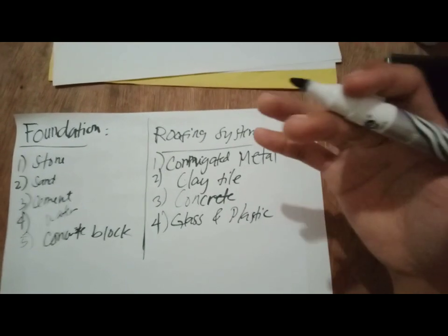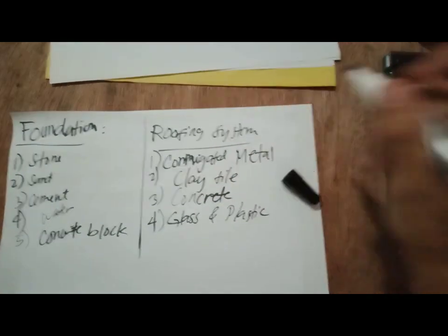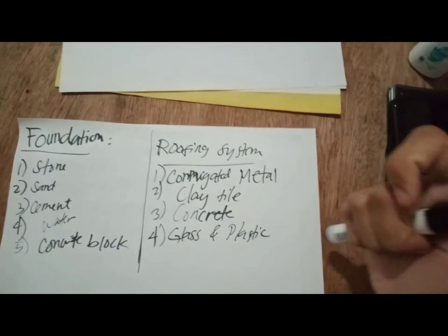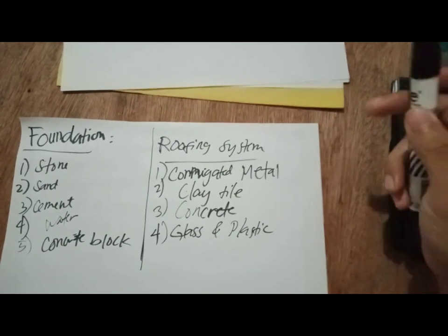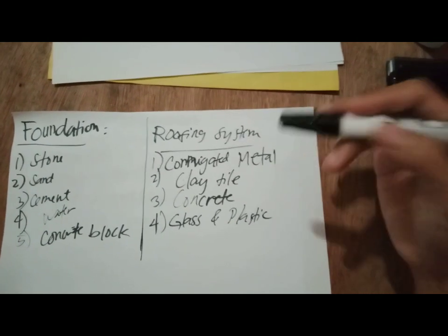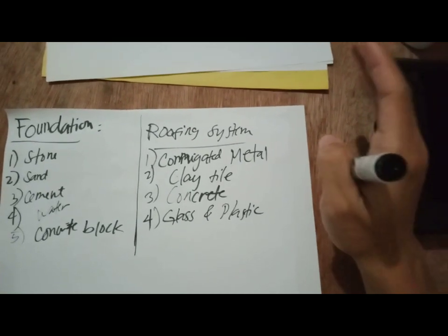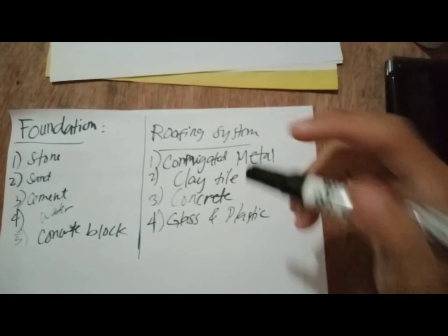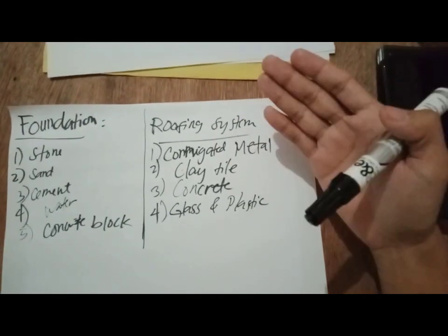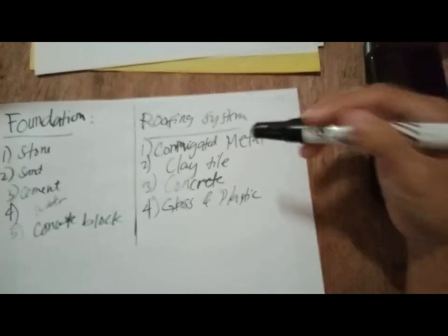So in order to adapt to the thermal expansion brought by this exposure to high temperature, the corrugated type of this kind of material provides a movement whenever there is thermal expansion. In return, the thermal stress that may be imposed on this material will be lessened because of this corrugated design. So that is the main purpose.